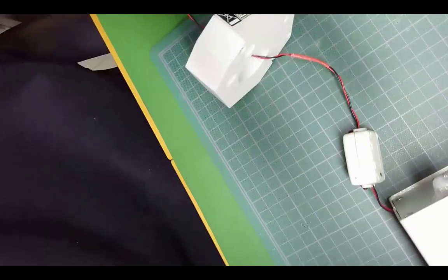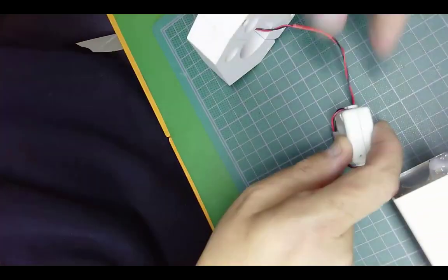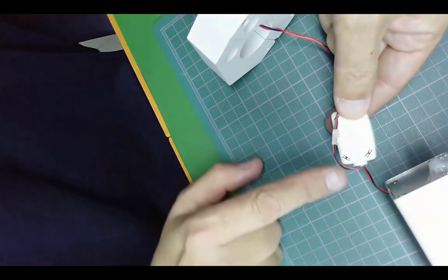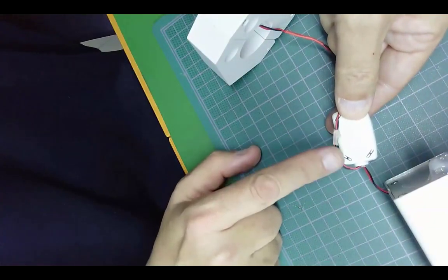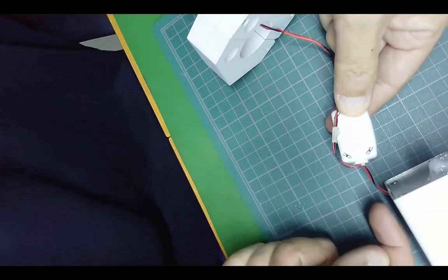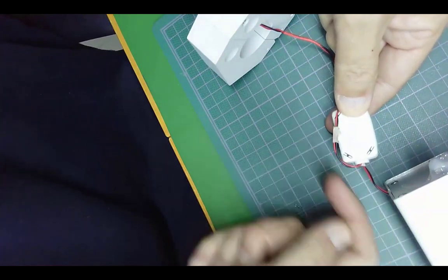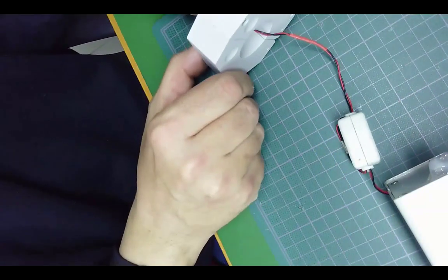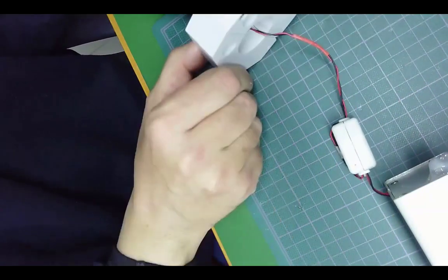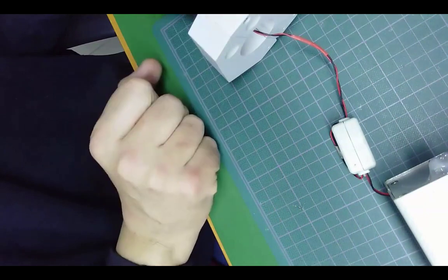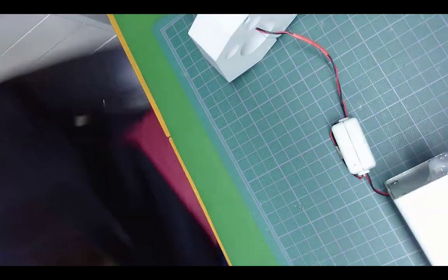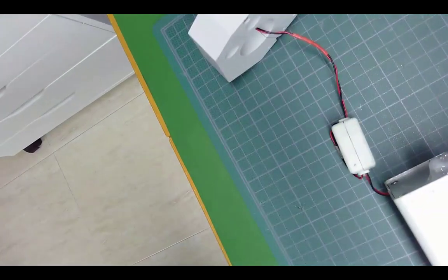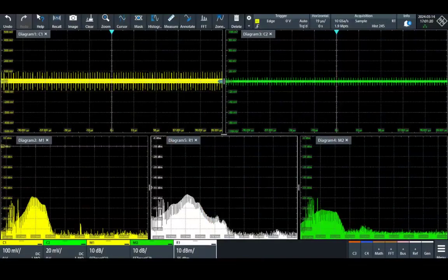You can see that with 2 turns in the ferrite, I am introducing, I don't remember exactly from the data sheet, 800 ohms, and the 800 ohms try to limit the common mode current that is going in this direction. It's important not to move the current probe. The current probe must be exactly in the same position where you measured the reference signal. If we switch to the screen of the oscilloscope again, you can see the difference.